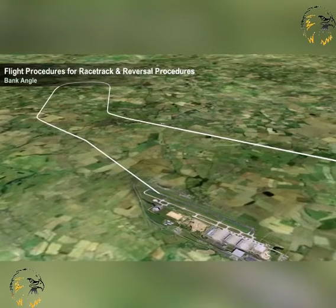Bank angle. Procedures are based upon a bank angle of 25 degrees, or the bank angle giving a rate of turn of 3 degrees per second, a Rate 1 turn, whichever is less. Descent. The aeroplane is to cross the fix or facility and fly outbound on the specified track, descending as necessary to the specified altitude. All further descents should only be made when established on the inbound track. For reasons of safety, all turns are level turns.